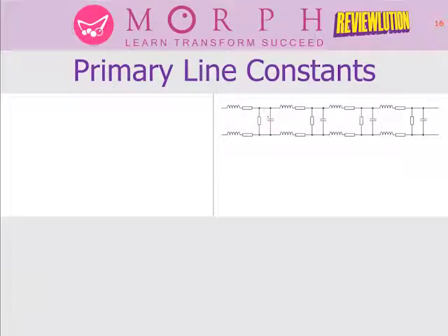Now this is distributed evenly all throughout the transmission line. Gaano man kahaba yung transmission line. But if the transmission line is medyo mas maliit na siya kumpara sa wavelength natin, mas maganda na i-lump natin yung mga components na to per length na lang. No? So that is why we could simplify it into a form like this, no? Like inductance per length, resistance per length, conductance per length, and capacitance per length.